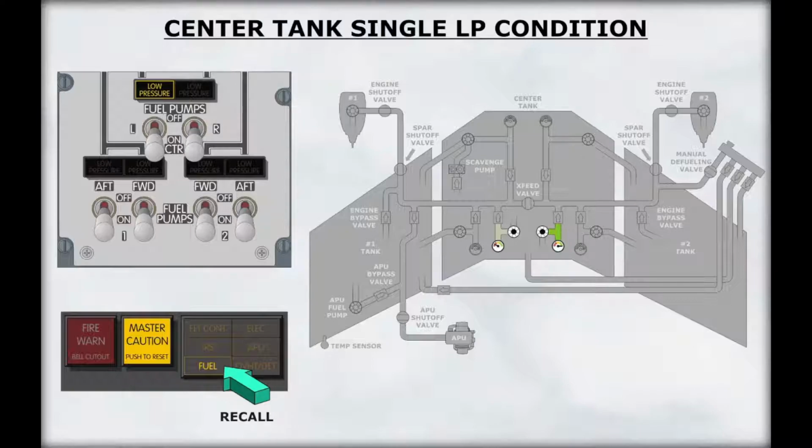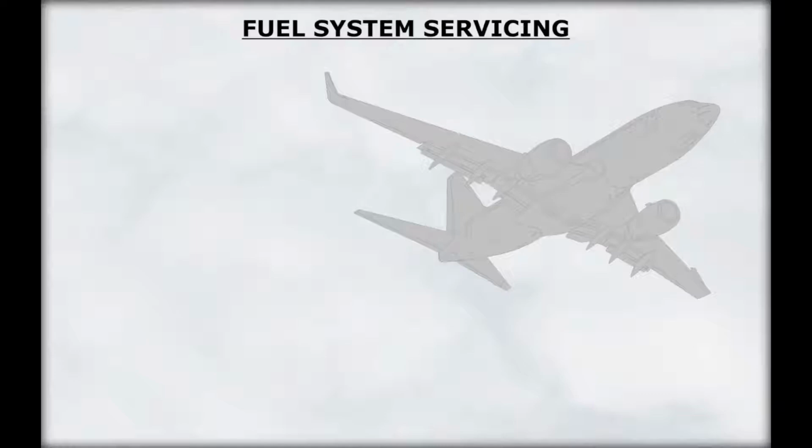The fuel annunciator light and master caution lights will illuminate on recall if one center tank low pressure light is illuminated. We will now cover the servicing of the fuel system.